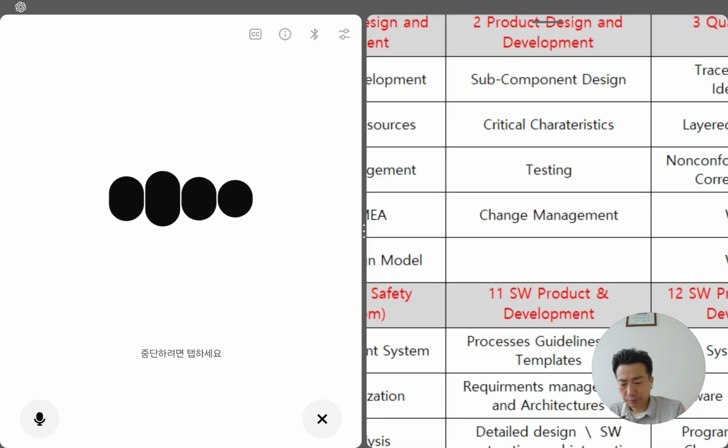1. Surround view camera, SVM: lens alignment, tilt, rotation, focus. If misaligned, image distortion occurs, impacting safety. Field of view, FOV, coverage must meet exact degrees to avoid blind spots. Image resolution and pixel defect rate must meet customer minimums, no excessive dead pixels. Waterproofing, sealing, IP rating: failure could cause fogging or short circuit in rain. Connector pin quality and ESD protection are critical for stable signal transfer.